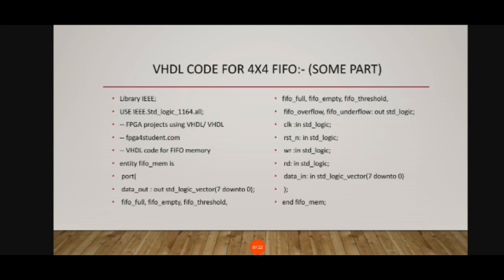Another benefit is that VHDL allows the description of a concurrent system. VHDL is a data flow language in which every statement is considered for execution simultaneously. Unlike procedural computing languages such as BASIC, C and assembly code, where a sequence of statements is run sequentially, one structure at a time. A VHDL project is portable, being created for one element base. A computing device project can be ported to another element base, for example VLSI with various technology.